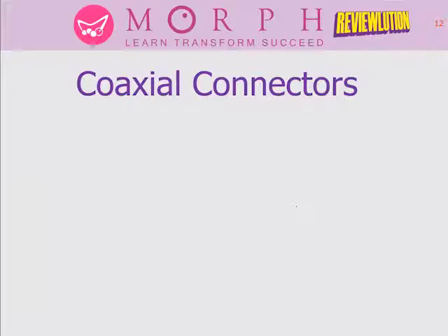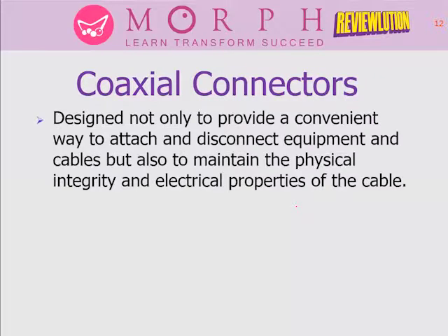Mga specific connectors na ginagamit natin na lumalabas na rin sa board exam. So coaxial connectors are not really just para lang may convenience sa pag-attach and detach ng ating mga coax into the ports and terminals, but also for the integrity. No? So ang hirap din kasi pag yung coaxial mo is sa splice mo using manual splicing lang. Kukonect mo yung mga coax sa mga ports nila by manual splicing, so that would not preserve the integrity and the quality of your transmission. So there may be loose contacts that could obviously compromise talaga sa communication mo.